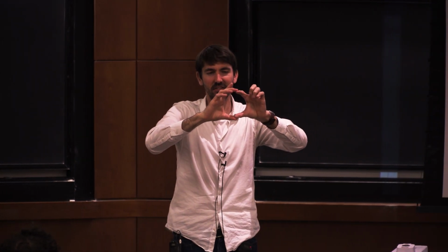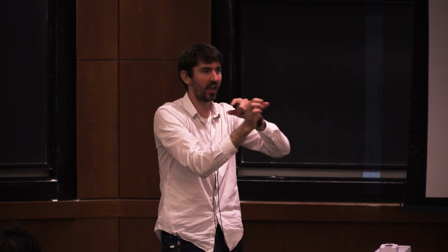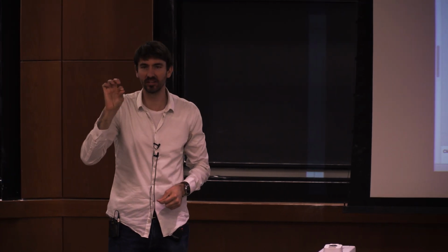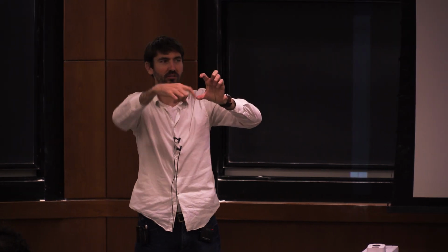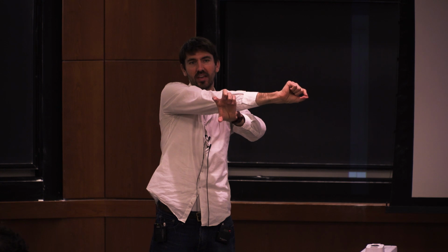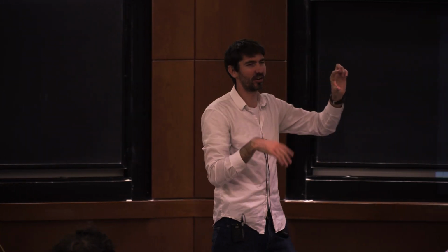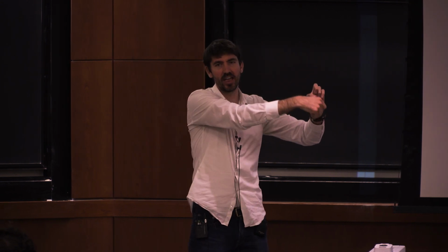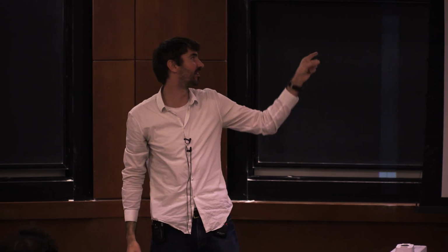So you're like, uh-oh. So what you do is you actually transfer that energy from here to a small measuring device that has an incredibly small capacitance. And that's how you get the sensitivity. So you actually transfer this one single pixel to a sensing pixel, which has excellent sensitivity. It actually is even worse than that. It turns out that that sensing pixel still has 1 over F noise. All of electronics always have 1 over F noise. And therefore, they actually transfer it over and take it off and put it over and take it off multiple times to get to this single electron sensitivity.